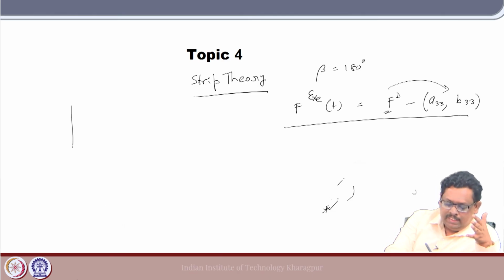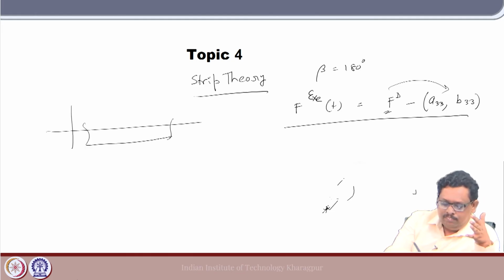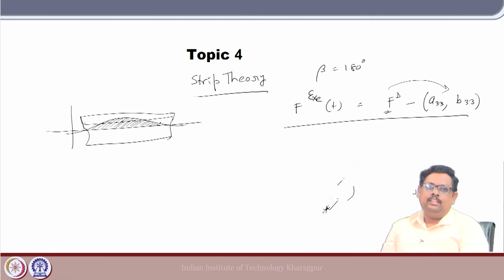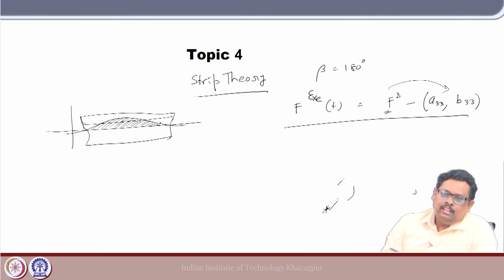If you remember that extra buoyancy force we discussed, suppose this is the ship, and then you superimpose the wave. Because of this wave, this extra buoyancy force can act as an exciting force. That also we discussed. And the moment because of this extra buoyancy force, that also we can take as an exciting moment, right.